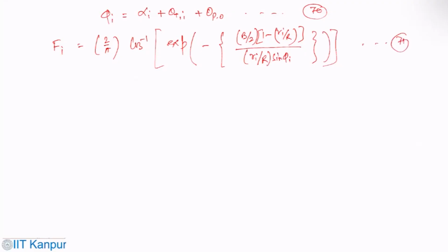Now the lift coefficient and angle of attack can be found by iteration or graphically. Typically the graphs could be like this: one can have a variation of alpha versus CL, it goes like that, and some curve is there. So this is alpha I, this is CLI.